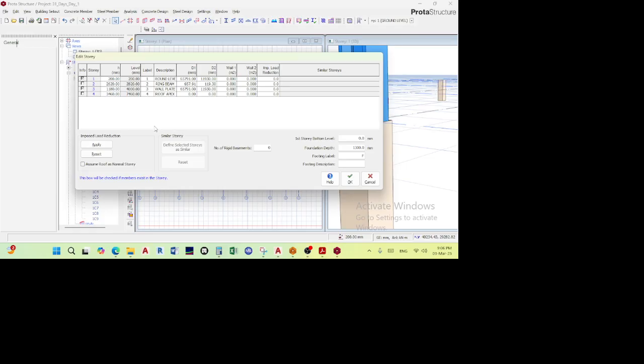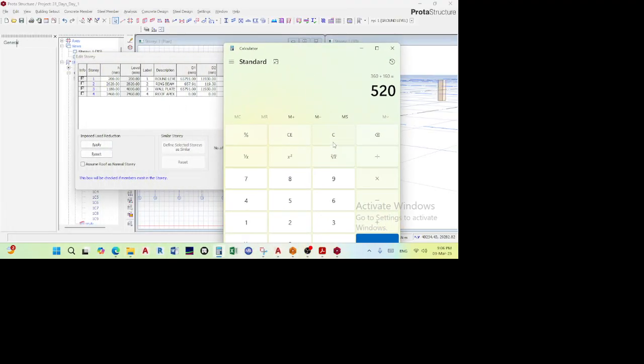Oh, okay, I understand. Because we were placing it on the wall plate and it's going to the ring beam, the difference between the wall plate and the ring beam is what we had at the beginning. So now what we need to subtract is the ring beam minus the ground, right? So the ring beam is 2820. Let's pull out my calculator. 2820 minus 200, right? And therefore it should be 2620.